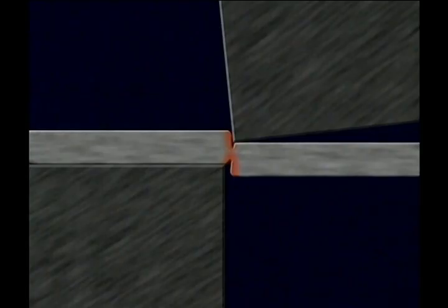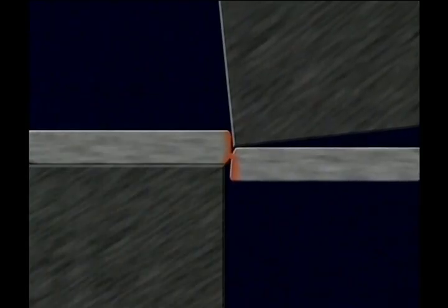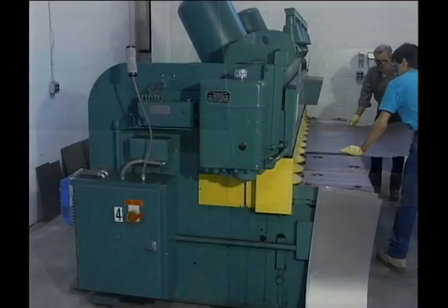As the blades penetrate the material, a crack or tear, called the slit plane, develops on both sides of the material, separating the stock. On most shears, the upper knife is aligned at an angle of between 1/2 and 2.5 degrees to the lower blade. This angle helps concentrate the shearing forces and ensures that the sheared workpiece, called the drop, will not become wedged between the two blades.